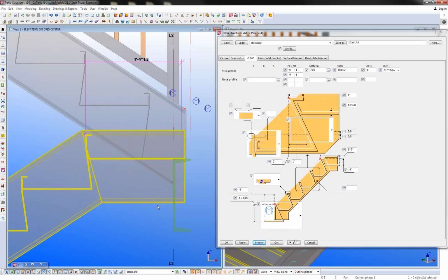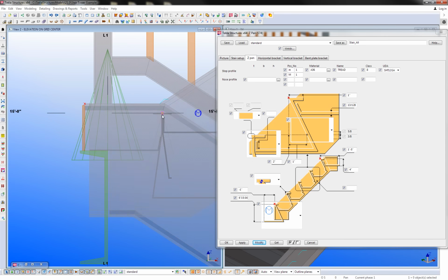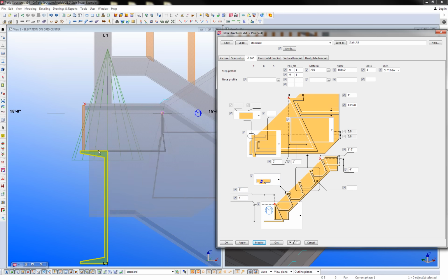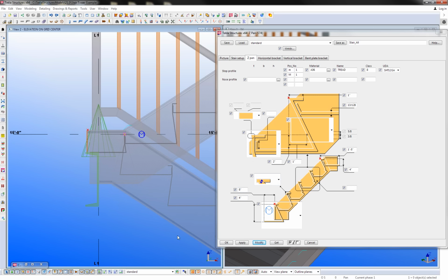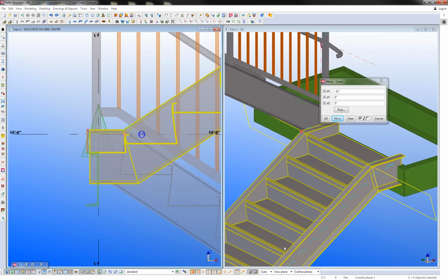And then I'll finish this off in a moment, but first I want to come down here and adjust this bottom pan. So this is still being dimensioned out as if it were coming down to a concrete floor. So really all I need to do is set its depth, make sure it only comes down about 4 inches for this, the concrete decking. And then I want it to turn out, this was at 8 inches, so I'll just set the same thing. I'll set it to 8 inches. And now my pan's going to kick out and rest on top of that landing beam. So again, all very visual, very dimension-based. I just come through and adjust the dimensional properties that I want until I get the actual stair layout that I'm looking for.